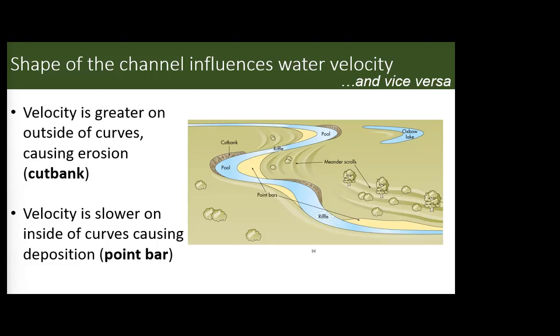We could go to White Clay Creek just off of North Campus, where am I going? This way. If we go to White Clay Creek, we can see these point bars and cut banks pretty easily. At every point bar, on the opposite side is going to be a cut bank, and vice versa. Point bars, because we have this area of deposition, indicate lower velocity, low energy. That's where we can get stuff to settle out. If we have higher velocity, we're going to be cutting stuff away and bringing more material in. So this is all defined by the velocity and energy behind these channels.